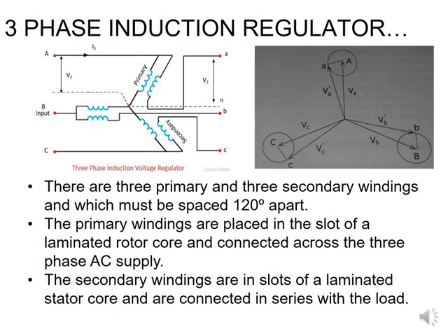And how does this do the regulation? If you look now at the right-hand side, you can see that you've got VA, VB, and VC. Then you've got V'A, V'B, and V'C. If you look at the apostrophes, you can see that they have smaller voltage values than the ones without the apostrophe. The ones with the apostrophe, with the small letters in them, represent the load voltages, whereas the plain VA, VB, VC represent the voltages at the start on your supply side.